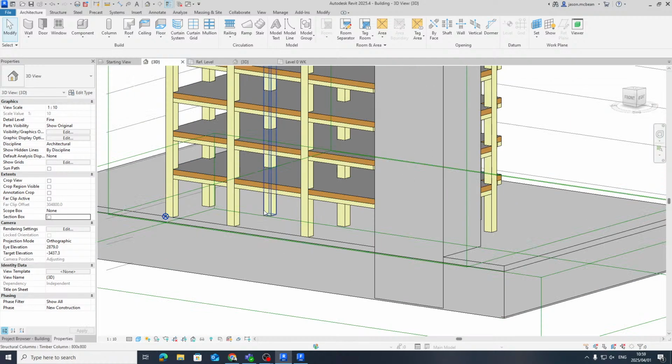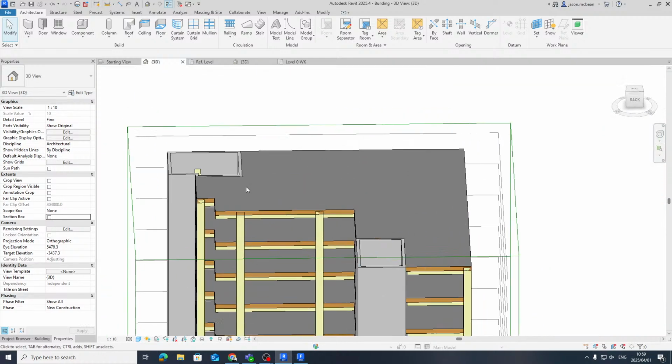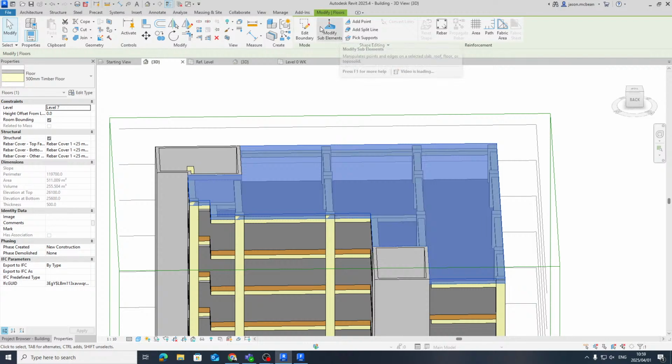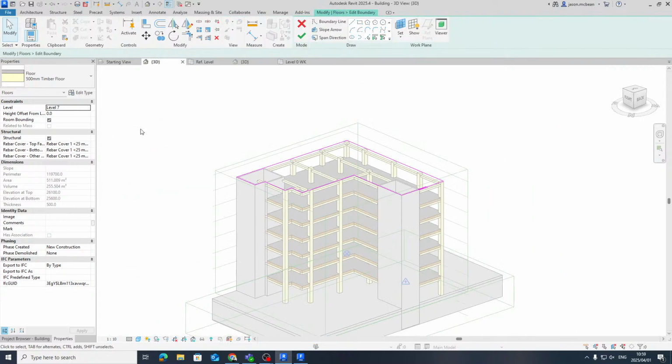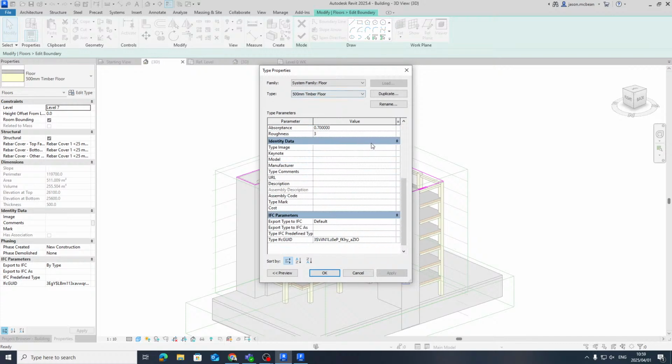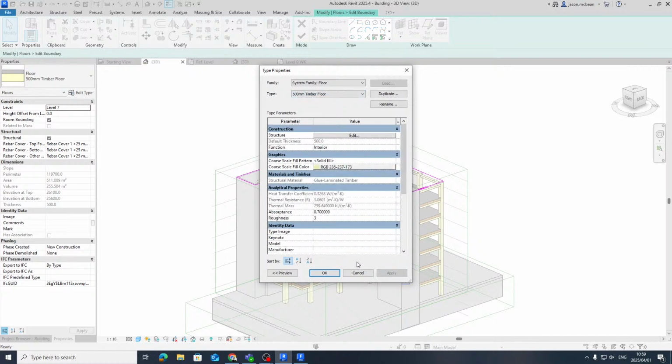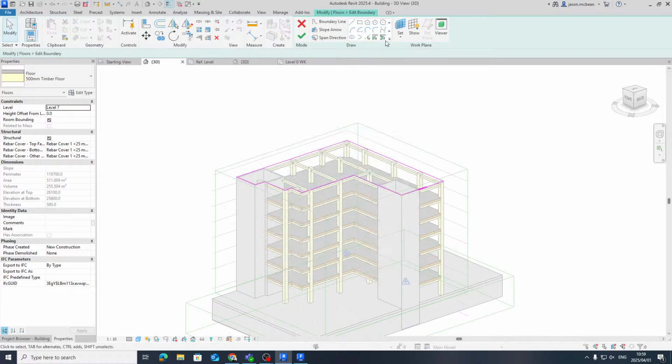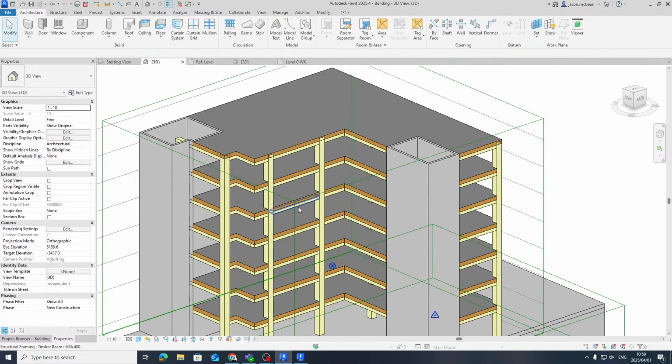So for example, if I wanted to model the stuff in Revit, you'll need to understand Revit. It's got push-pull, you'll have to make up floor components. ArchiCAD is doing the same thing. So to model stuff very quickly, it's not that easy, because you've got to go and set up your floors correctly. For example, I just want to show you this timber beam.